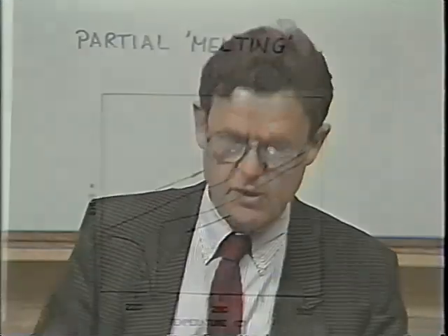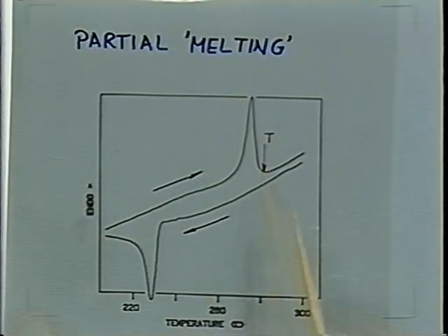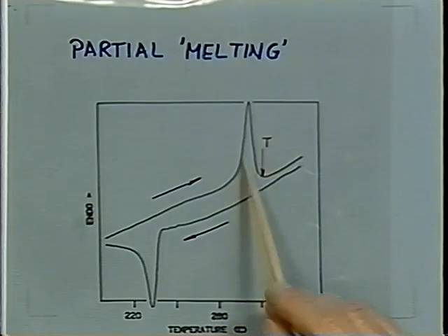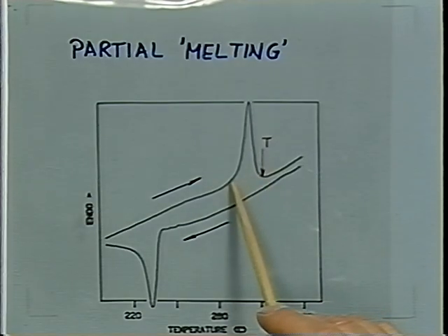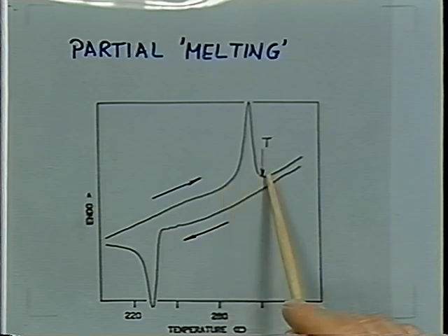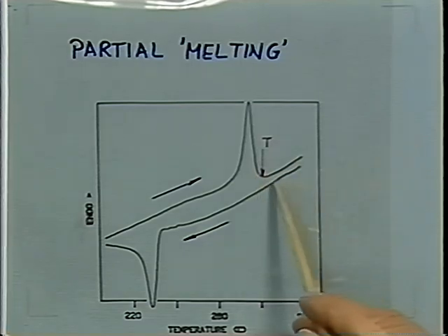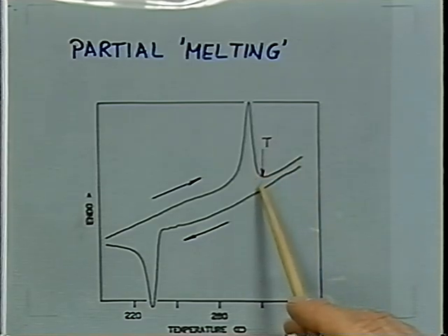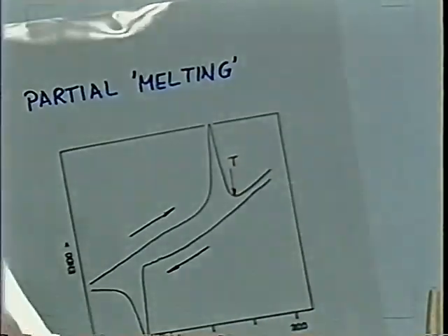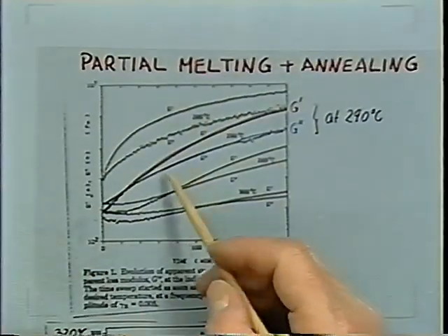Very interesting is also the rheology just above the nominal melting temperature. We would melt our sample, but because it's a broad melting transition, we will not melt the sample completely if we don't heat to a very high temperature. If we stay at 285 up to 300 degrees C, as you will see, the sample shows some very interesting behavior. Now this figure is very crowded, and I wanted to pick just 2 curves.